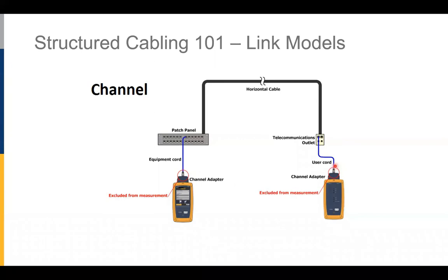Sometimes we're going to add an extra outlet when we're installing wireless access points. Well, I'm only installing 1 wireless access point, but the standard recommends we bring 2 cables there. That gives us the flexibility in the future to add an additional access point. Again, the standard is the experience of the industry. What has worked well for me? What hasn't worked well for me? Oh, I didn't install all 4 pairs. That didn't work well for me in the past. Let me recommend that to people in the future.